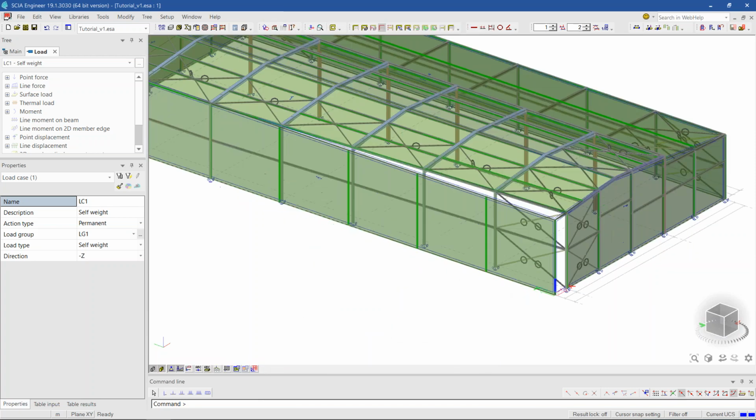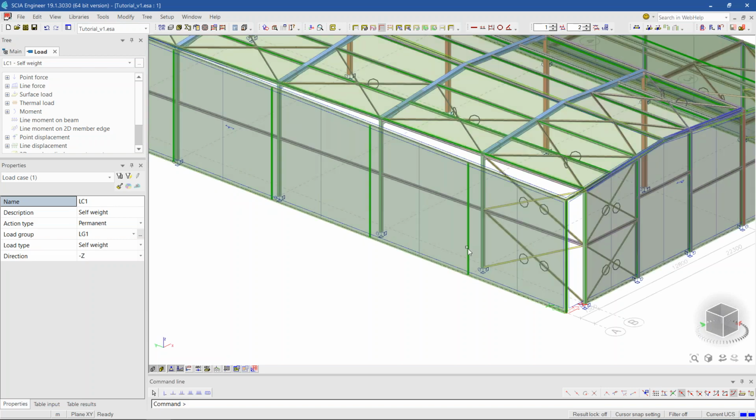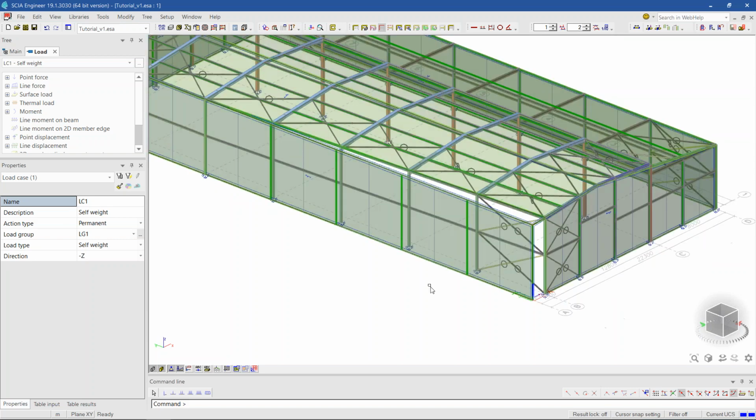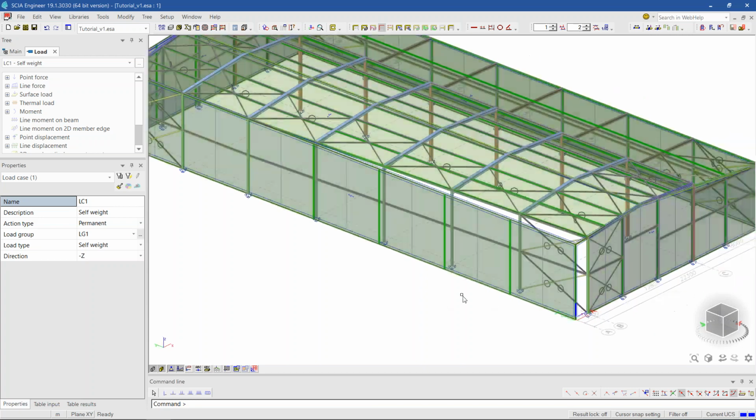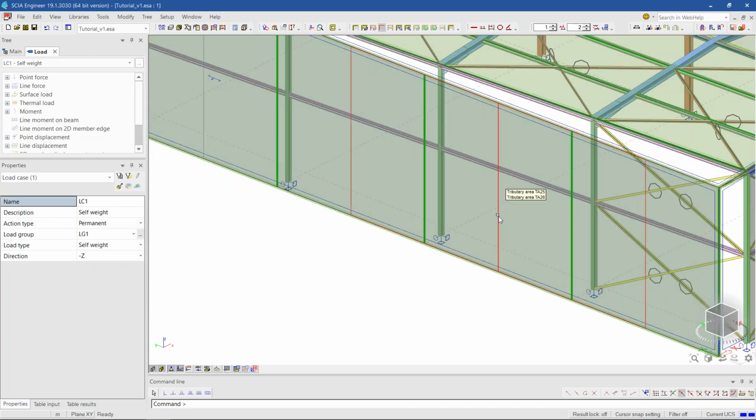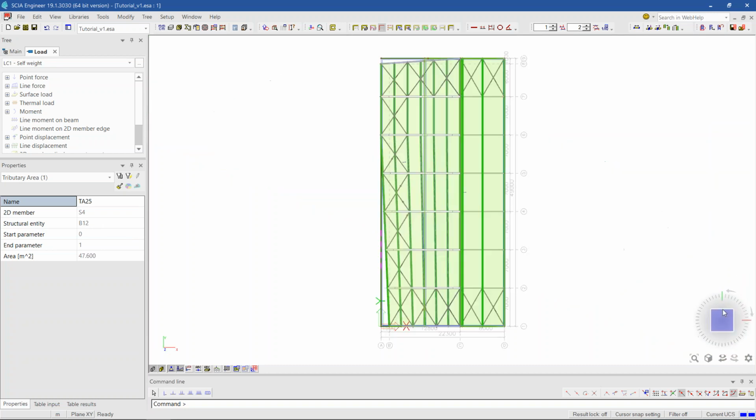When you show that, you see this big green line which says in this place I have detected a load bearing element. And also I here have this so-called tributary areas. When I select this tributary area, I can see this tributary area is carried by element B12, which is this column. And the same goes also for the roof, which is a little bit irregular.